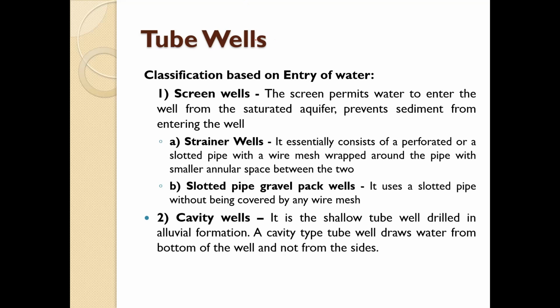So the screen wells. The screen permits the water to enter the well from the saturated aquifer, and prevents the sediment from entering into the well. So you might have seen sometimes in the lining itself, the well screen has been placed to prevent the sediment from entering the well.